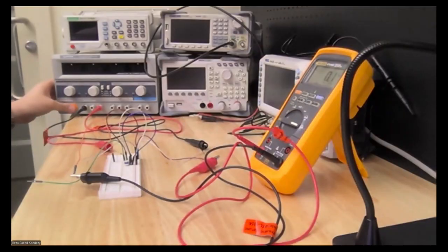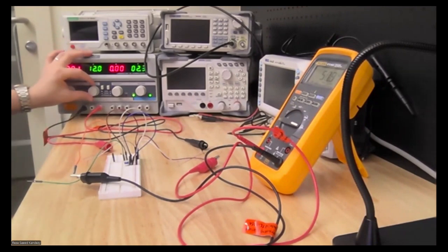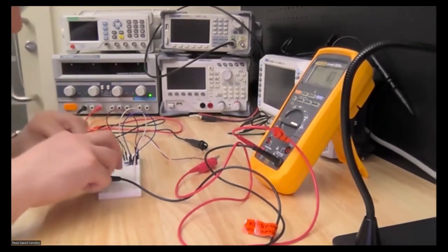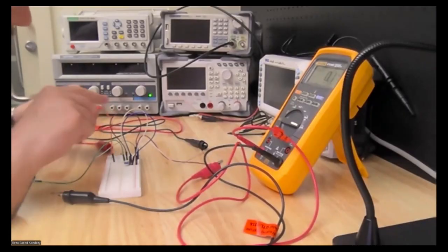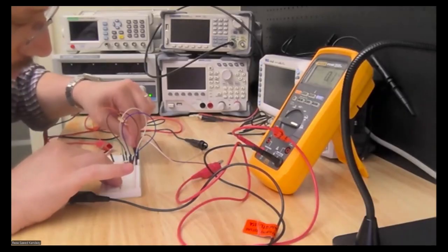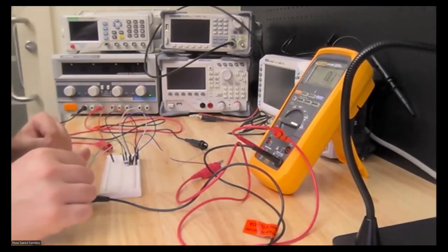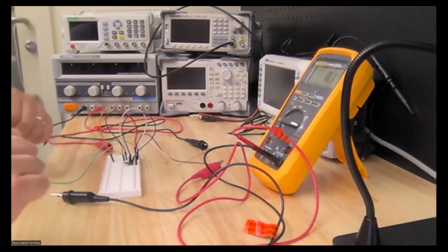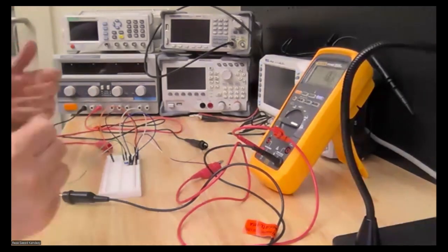Okay. Now I am gonna turn on my circuit. I'm applying 12 volts in my source, and my meter reads 51.4 microamps, which is injected into my base. Now that I know my base current, I want to see what my beta is. So I want to check my collector current. Using the formula that we mentioned before, we can calculate the beta.